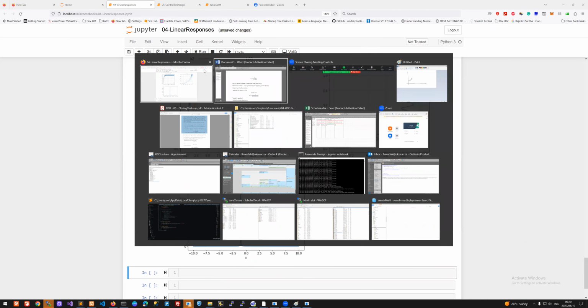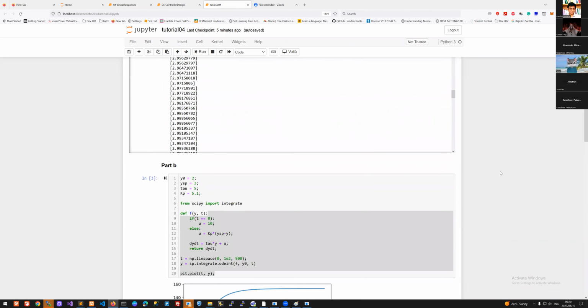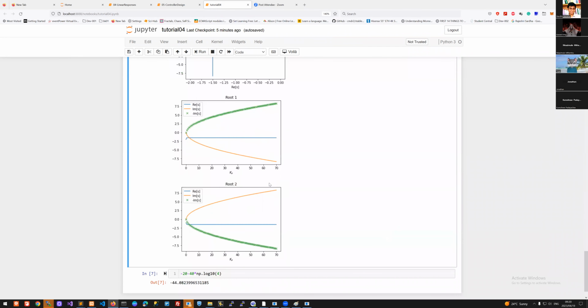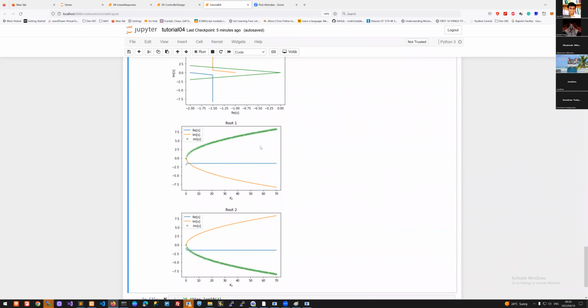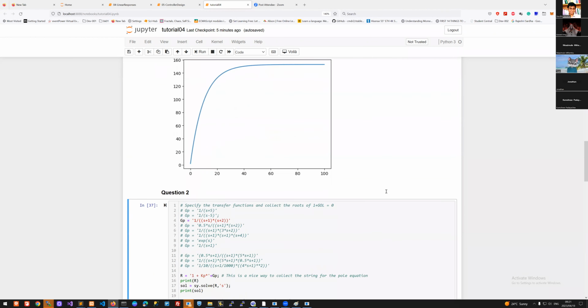If you find the equivalent second order process, you'll see those oscillations there. And that's what we detect here. So simply by looking at these graphs, we can tell, yes, there'll be oscillations. The imaginary parts are not zero, but the real part is negative. So 0 is here. You can see the real part is below that. And you can also see that here, the real parts of these two roots are always in the left-hand plane. Okay, so that's the second order case.